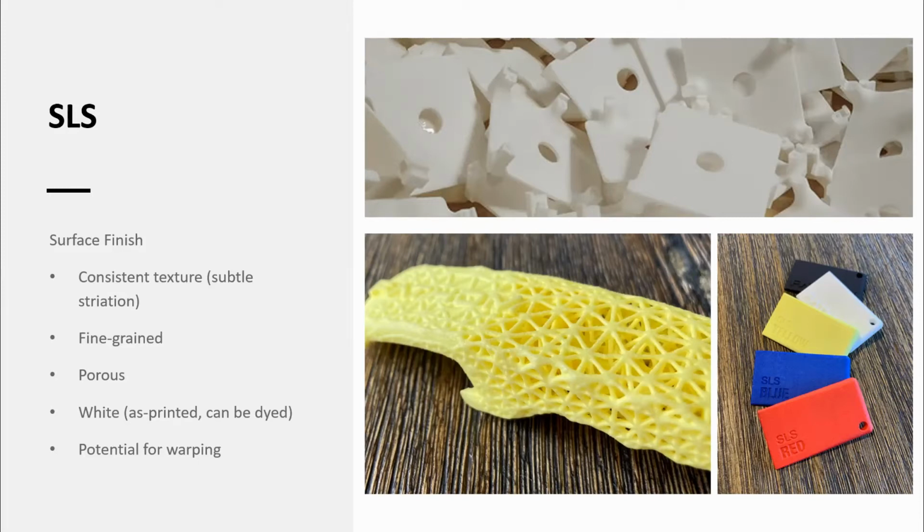For parts that have flat, thin walls, we always recommend that ribs or gussets be incorporated, and holes on flat thin surfaces can benefit from bosses, which is very similar to part design for injection molding.